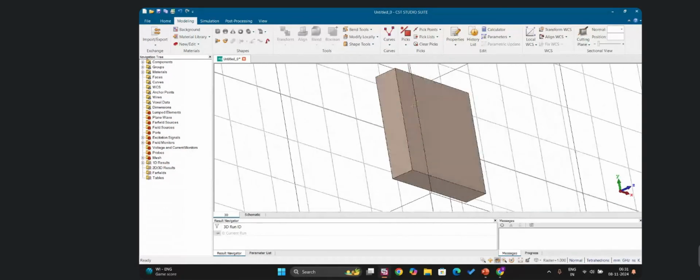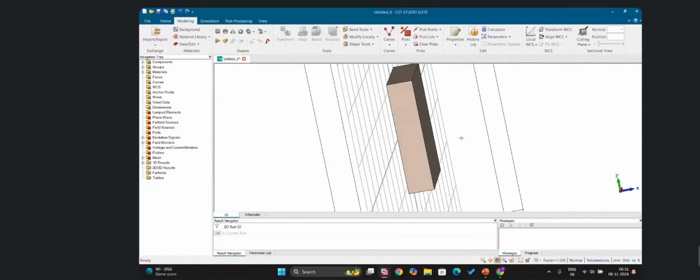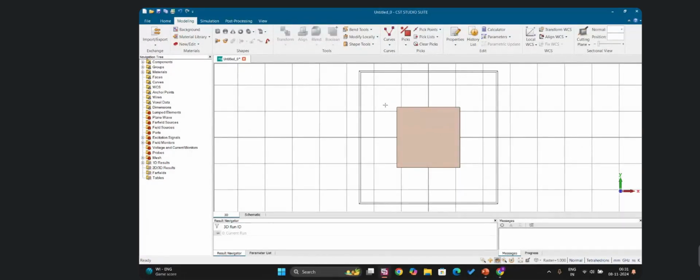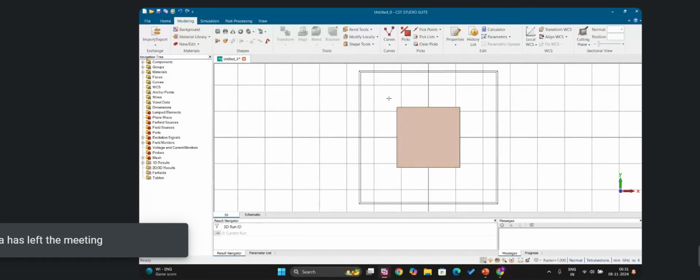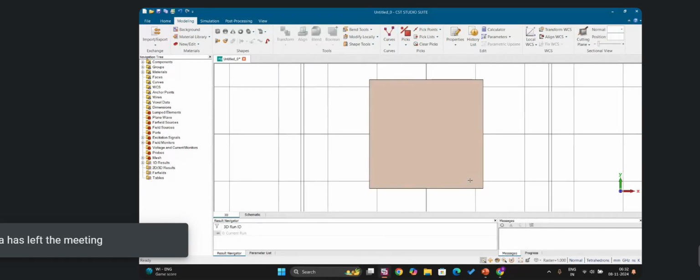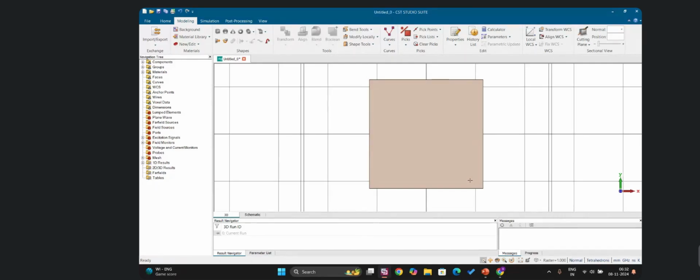You can see the substrate now. It is a rigid substrate. You can also design the FSS in conformal state based on the application. For radar application, we have to achieve the bandwidth as much as possible, so we have chosen the rigid substrate. The bandwidth is also achieved high in conformal substrate, that is your choice. And you can choose the material based on the availability of materials in the fabrication company.